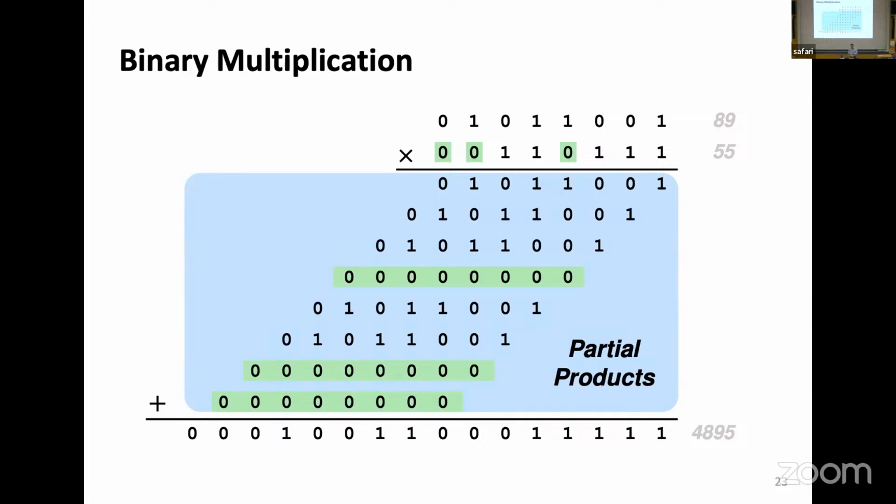Now, what do I do for the partial product? How do I generate these things? What functionality is needed? No. Shifts, well, I'm shifting them, but how do I come up with the number? It's either the number itself or 0. You could do it because you can do any logic function with a multiplexer, I agree. It is true, there's no laughing matter, but there's a simpler logic function. You AND the entire vector with that bit. If it's 1, you get it. If it's 0, 0 and something will be 0. So partial product generation is a sea of AND gates, if you want.